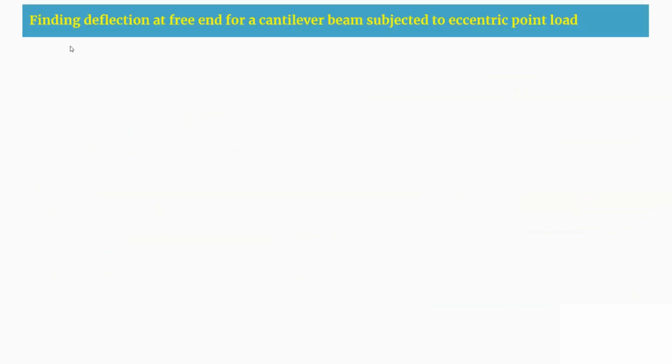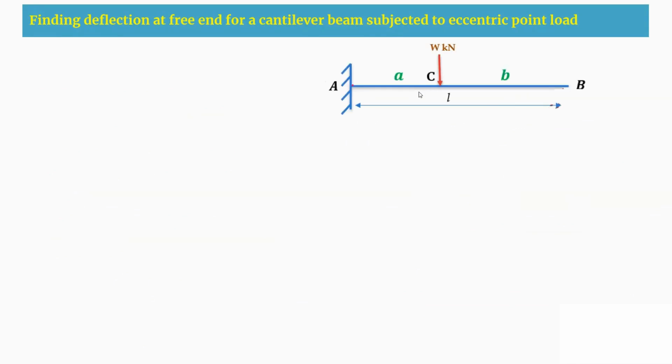how you are going to find the deflection at the free end for a cantilever beam subjected to an eccentric point load. This is a cantilever beam with an eccentric load at a distance A from the fixed end and at a distance B from the free end. For this beam, the deflection curve will be like this. At the fixed support there is no rotation and no translation, but at the free end, that is B, you have a deflection, delta B. This delta B I am going to calculate first.